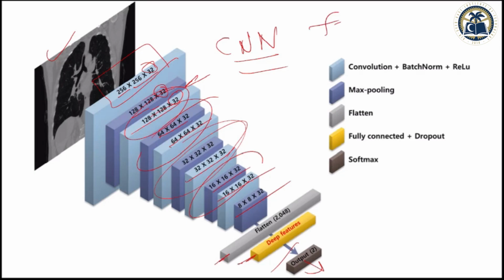So you must not try to do everything in parallel where you are only giving one X-ray per minute. It doesn't make any sense, because you process it in a few milliseconds or microseconds and then you are just waiting. So the most important thing is your budget, that is, how fast you want to process your data. So the sampling frequency, Fs, and then the clock that you are targeting. These are the two most important aspects to see how much folding you can do in your algorithm. How much should you fold? And obviously the fun is that you do everything in parallel so that you design something which is so fast.